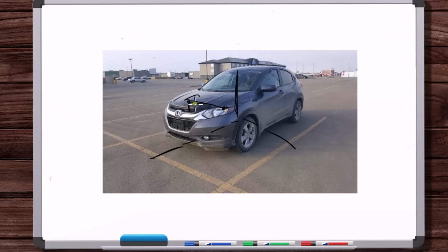I mean, that force oriented randomly like that could be causing the car to spin. That would be like a 3D case. So just because you have coplanar forces doesn't mean that you're going to have a planar free body diagram, unless those forces are in a plane of symmetry.